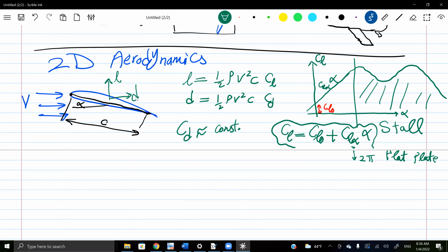Lift and drag, you will feel this really, and you can always feel the quadratic relation, because if you push your gas pedal a little bit, you will feel a significant increase in the force on your arm. If the velocity is doubled, the forces will be quadrupled. They will be multiplied by 4. So you can easily test that.